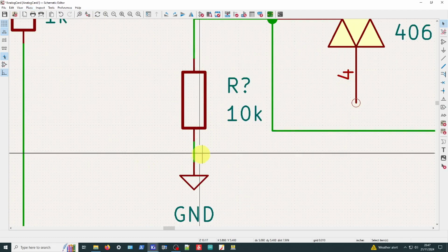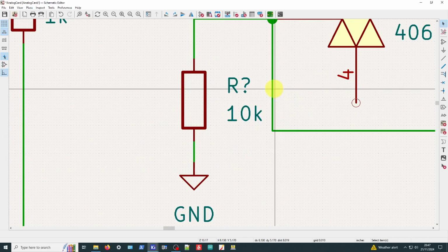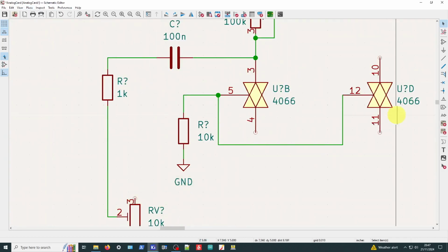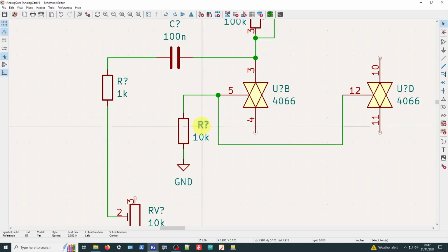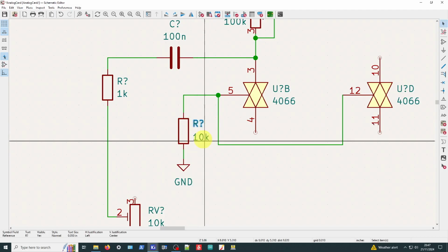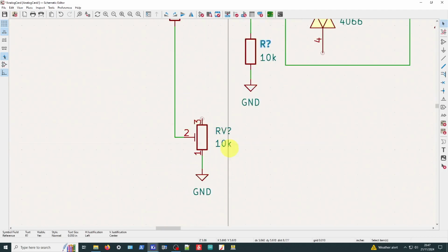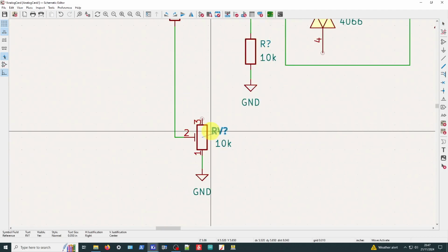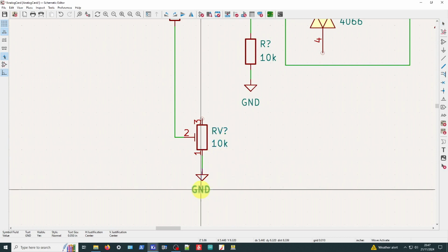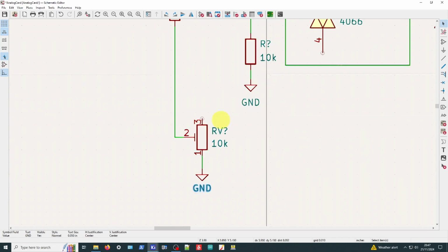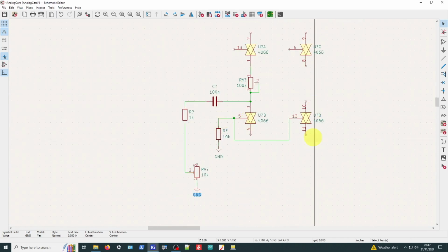Once you've started and you've got a few components on the circuit, I tend to just copy and paste them in and change the values as you go. You could also drag numbers around, the values and the annotated part number. Once it gets annotated, you can drag those around as well, just for neatness. I tend to pull them in a little bit, but that's all stuff you can do at the end when you've finished your layout. Okay, so here you are, we've made a start.